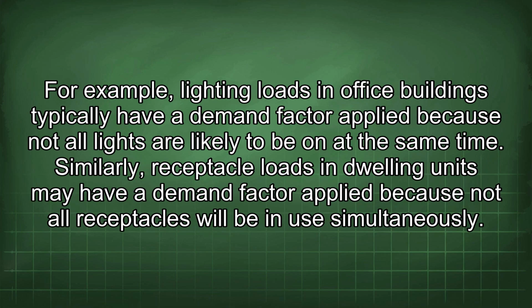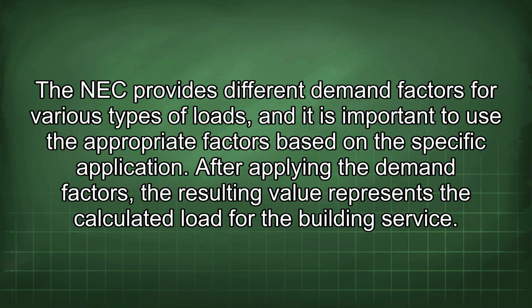For example, lighting loads in office buildings typically have a demand factor applied because not all lights are likely to be on at the same time. Similarly, receptacle loads in dwelling units may have a demand factor applied because not all receptacles will be in use simultaneously. The NEC provides different demand factors for various types of loads, and it is important to use the appropriate factors based on the specific application.